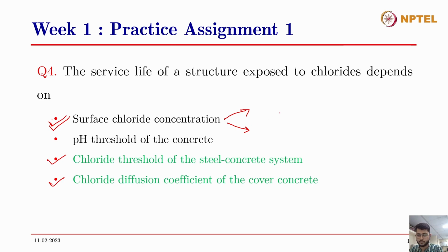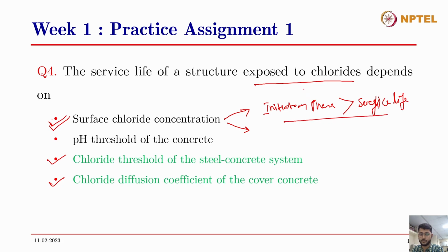But if we are comparing two structures exposed to chlorides in the same manner, and one structure has a high chloride threshold, so that the initiation phase is greater than the design life, then surface chloride concentration will not affect it.